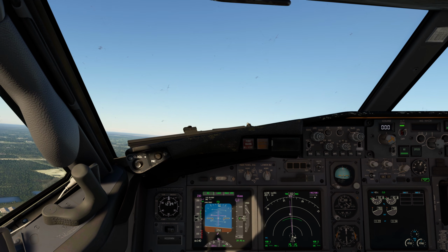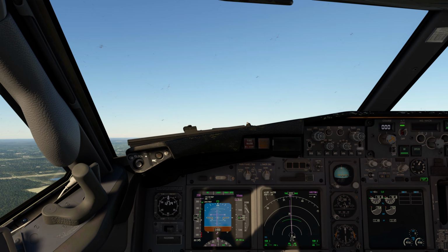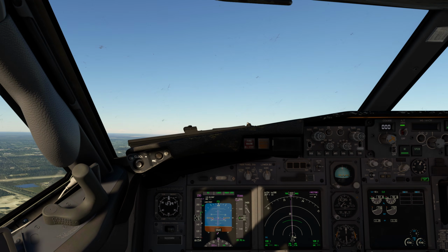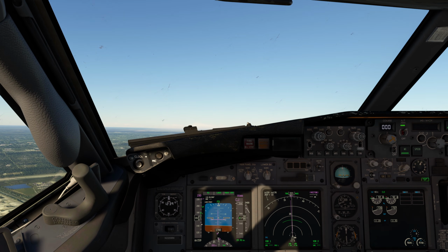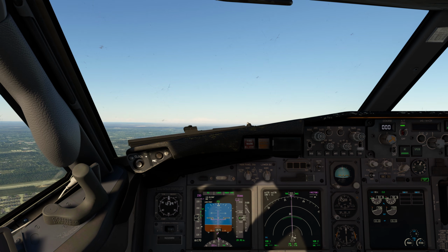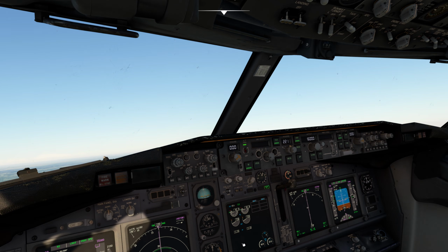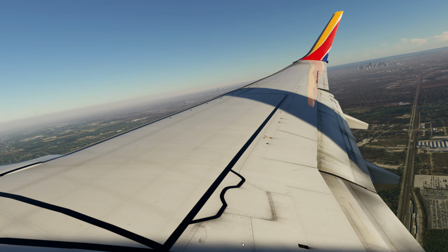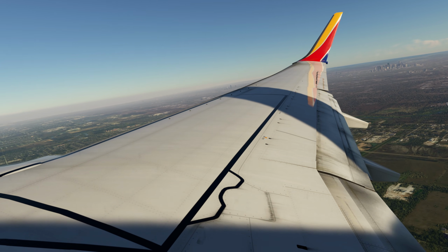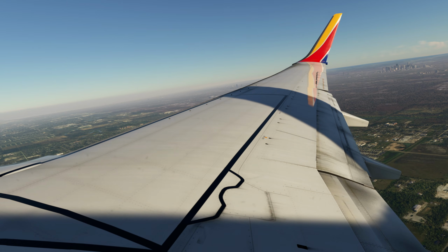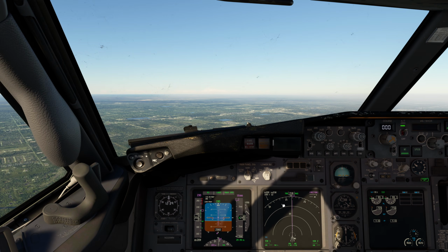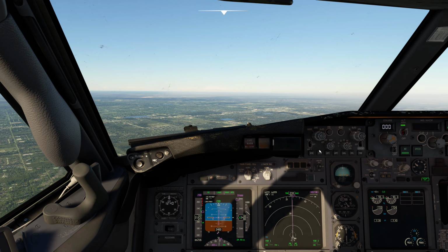Airspeed fell off big time there when I was doing that flyby view, but it looked cool. There's downtown. Okay, airspeed is building. We're going to look for that flap retraction speed. There's flaps 1, and let's go ahead and enable the autopilot. Okay, airspeed is building, flaps up, speed checks.